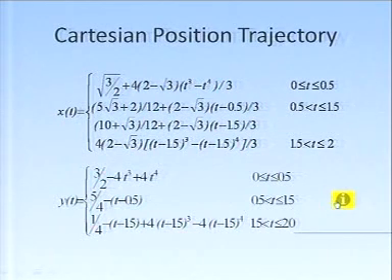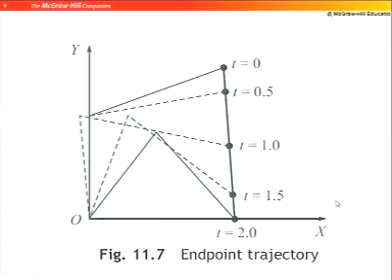If you want to see the plot, so now you see this is my plot. So, t equal to 0, t equal to 0.5, t equal to 1, t equal to 1.5. Note the difference, I wanted to move in a straight line fashion. Okay. So, if I do it in a Cartesian trajectory, this is the trajectory I have generated, whereas the corresponding theta 1s are shown here.